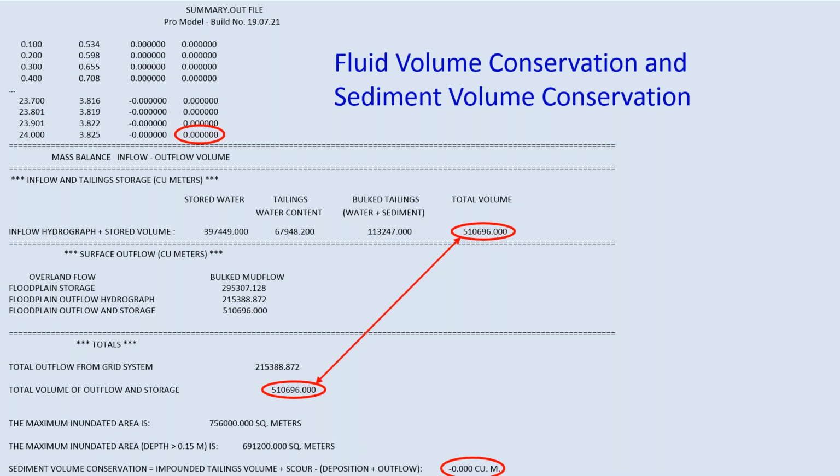So this is really critical, because the idea here is to get the volume pretty accurately from the stage in the dam or reservoir or tailings dam material. And this can define for you pretty accurately what the maximum area of inundation is.